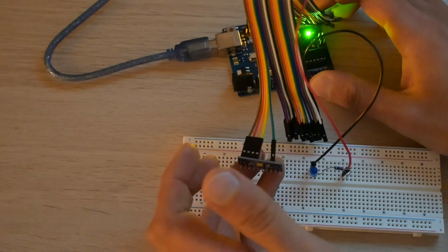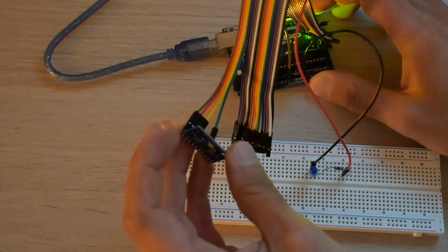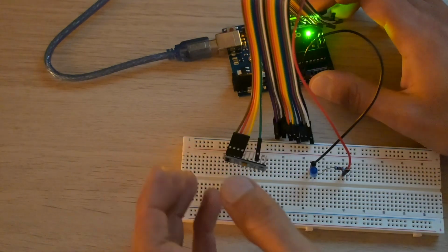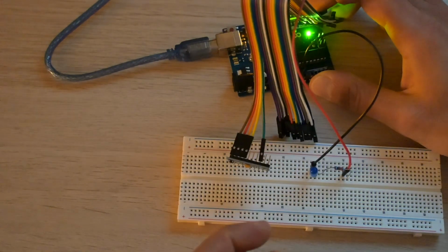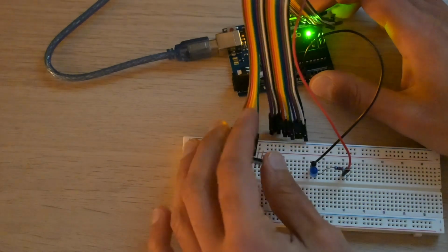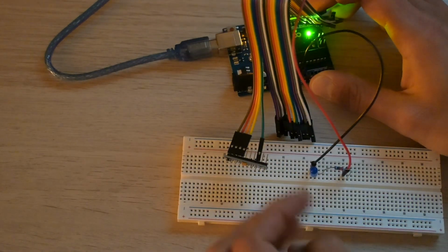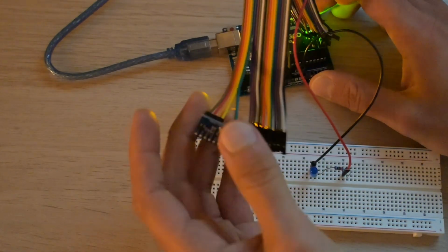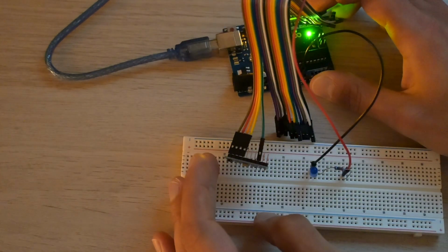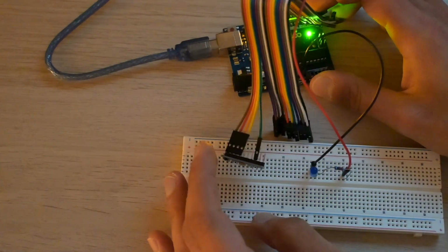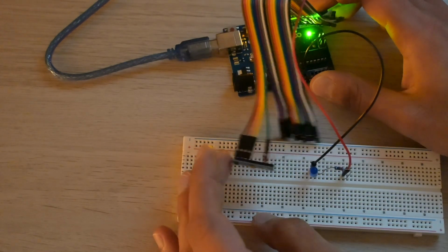And here, the objective of this experiment was to make the blue LED blink whenever the gyro was disturbed. But this resulted in a mostly unpredictable output, as you can see from the random blinking. The LED doesn't quite blink at the same time when I disturb the module. Sometimes it does, sometimes it doesn't. And the root cause is likely because I was sending an incorrect combination of commands when setting up the module. So further exploration would be needed here.